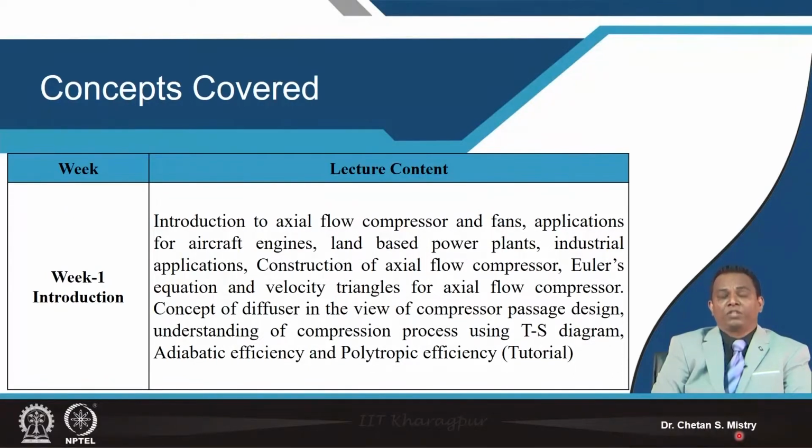Now all these things we have learned will make the base for us to move forward. Again and again, when moving ahead, we will be using Euler's equation and the velocity triangle, and the velocity triangle is the most important thing in order to realize what is happening within your axial flow compressor.